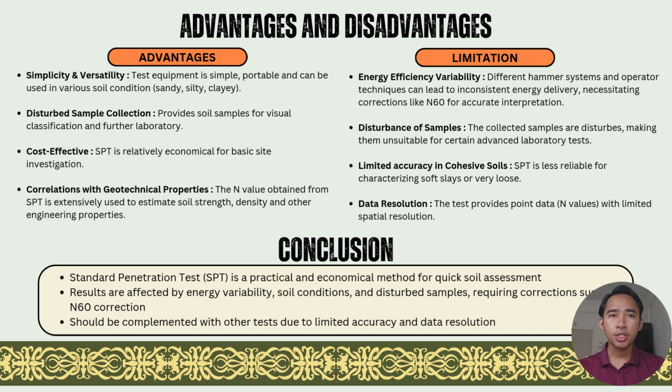However, there are limitations. The samples are too disturbed for advanced testing. The results can be inconsistent due to variation in hammer energy or operator technique. Furthermore, it offers limited accuracy in soft clays and only provides point data rather than a continuous profile.